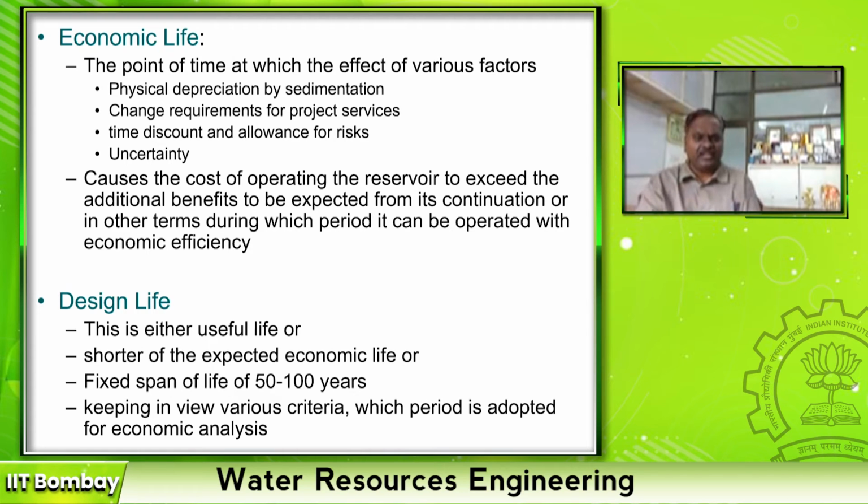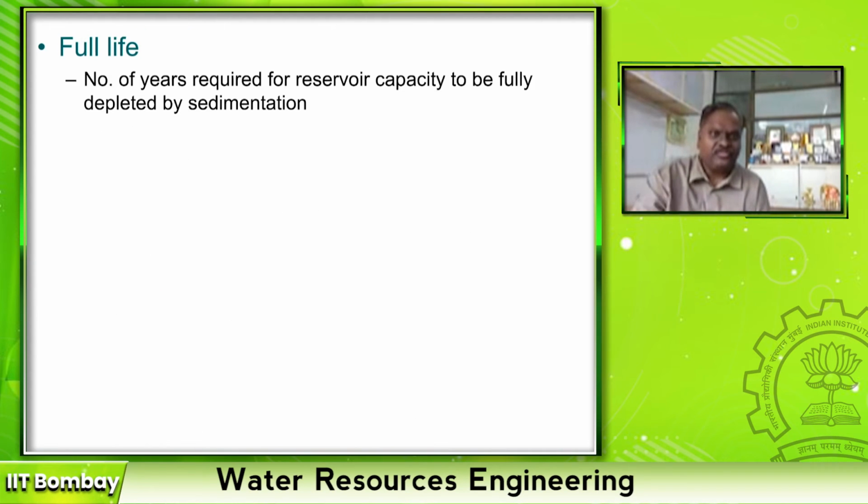Design life: every storage is fixed assuming 100 years or 50 years. That gives the dead storage volume. If the volume of sediment deposited is more than the dead storage, we say that it has reached the design life. Full life is the number of years required such that the reservoir is completely filled with sediments, that means no water can be stored in the reservoir.